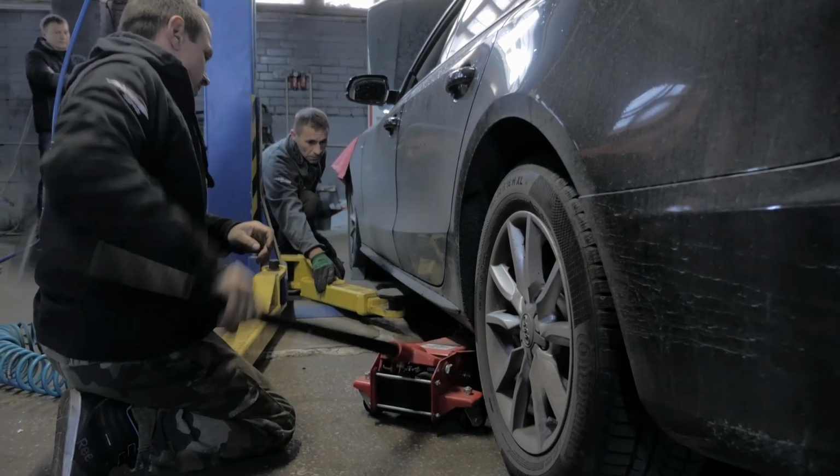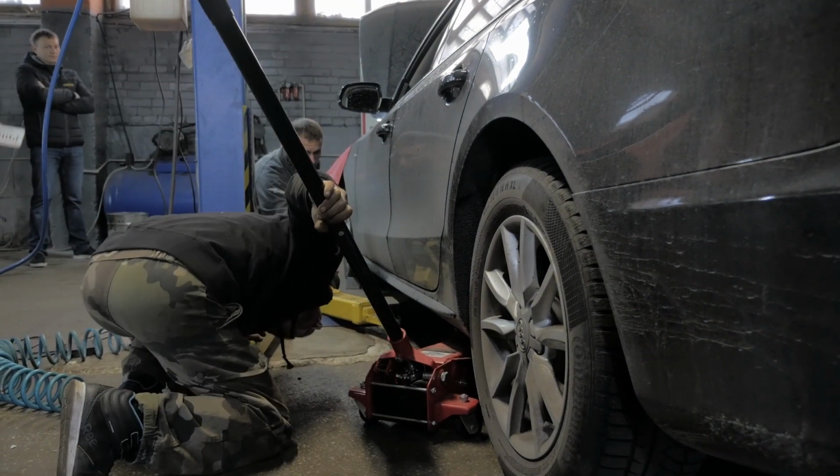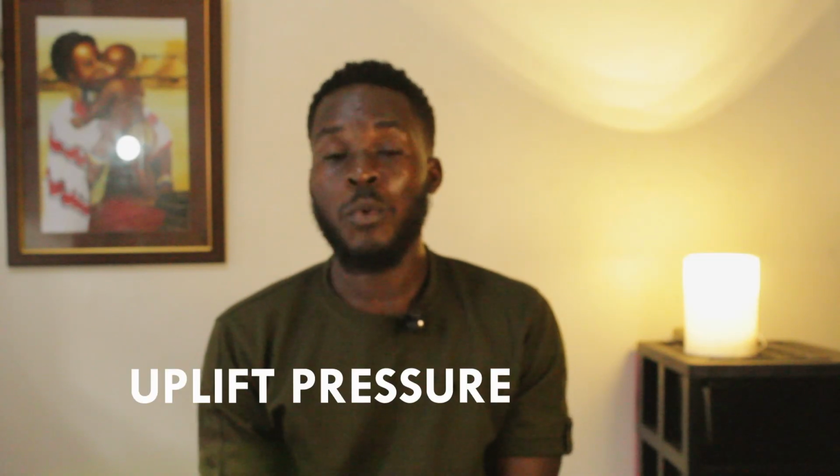Have you ever seen a car being jacked? Yes, groundwater can do the same to structures. There was a water tank project. Due to the need for maintenance, the contractor had to empty the tank in the night to do the routine maintenance. But the next morning, the tank was just above the ground. It was pushed out by groundwater. Imagine just waking up and then you find your tank up in the sky like it's going to heaven. That's groundwater. That's not bad concrete. It's groundwater because the uplift pressure was greater than the weight of the structure.